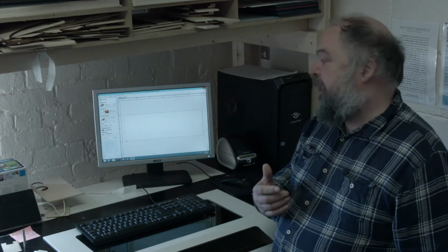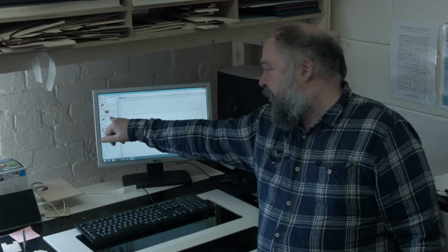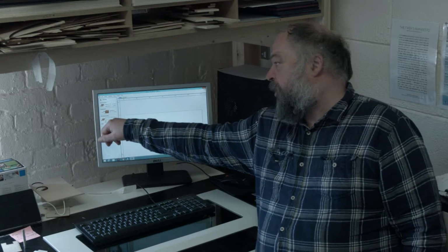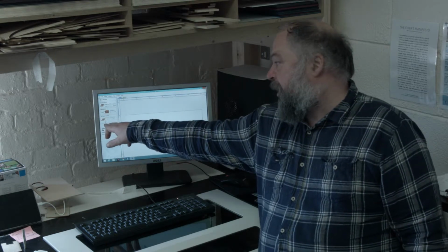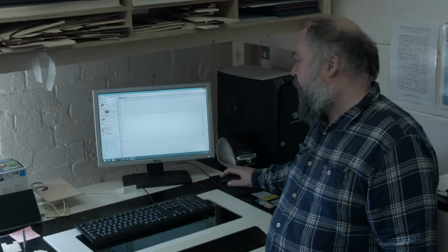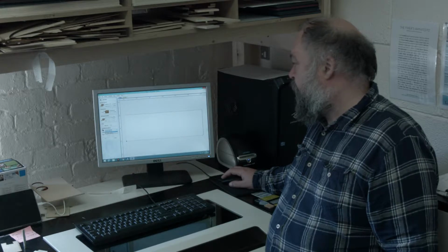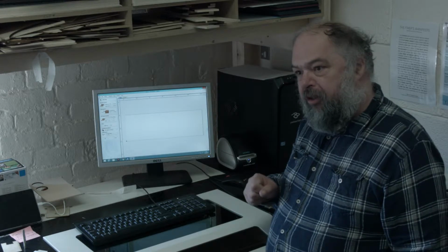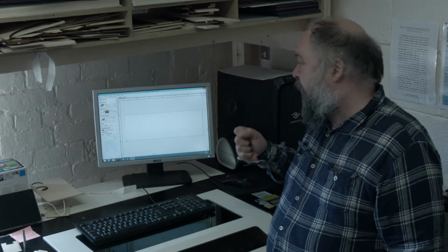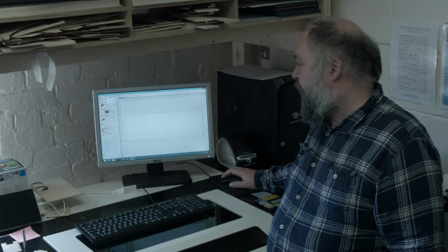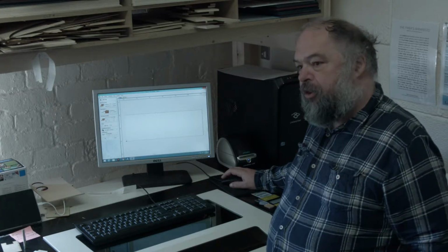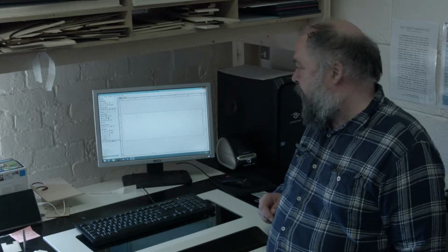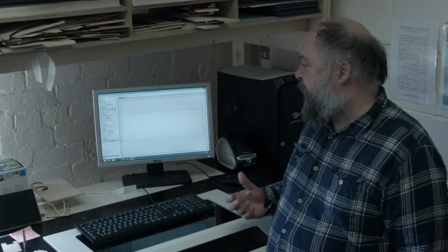Because it's working with 3D, you also have a datum point, so it's where you're going to work from. You can set it at any of the corners, or you can use an offset. I normally set it to the bottom left hand corner. Very strangely, it's software which is purely pixel based, even though it's doing the 3D images, so you set it to the highest value that you can. And you've also got an appearance, so I've set it to Canadian Maple. And we'll click on OK. So that's my workspace set up now.